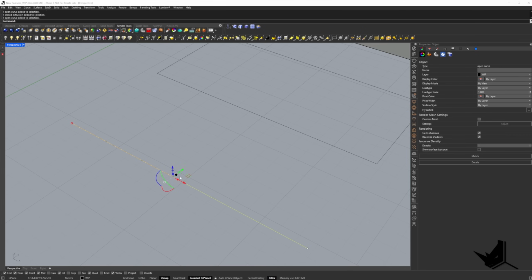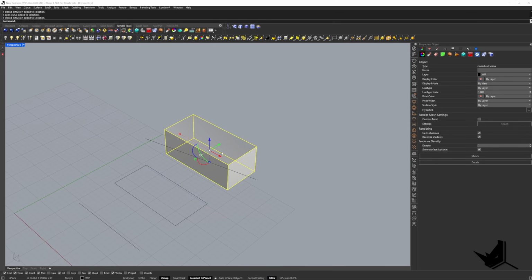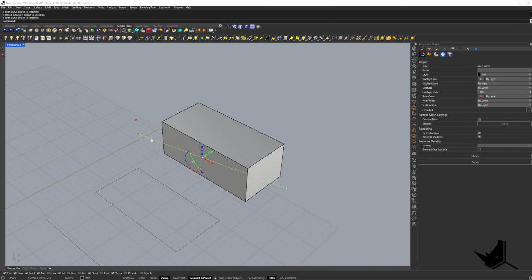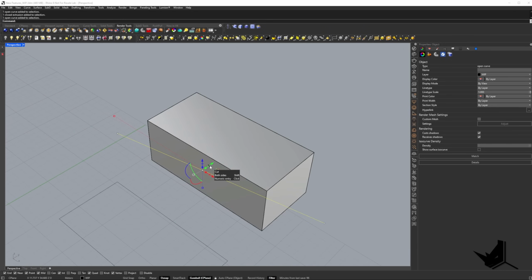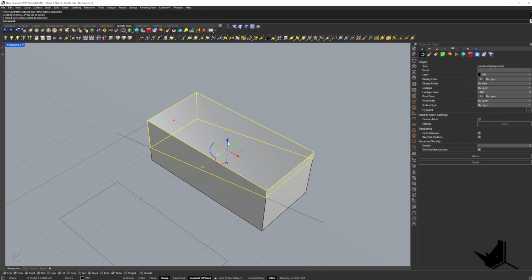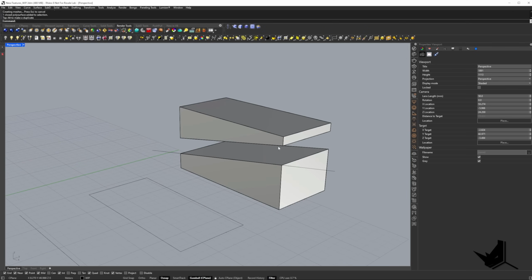We have the option to do this on both sides, and the way that this works, let's say that you have a box like this here, and then you have a curve that is aligned with its side. You can simply take this minus sign, drag it like this, and you will see that the box is gonna get cut in half, and we're gonna have a perfect Boolean split.